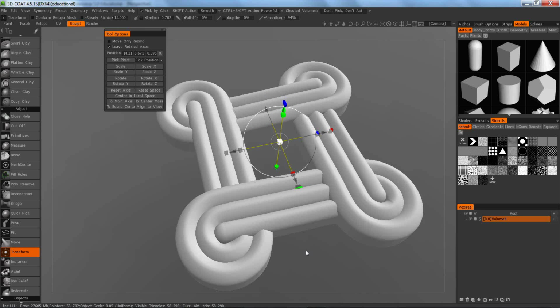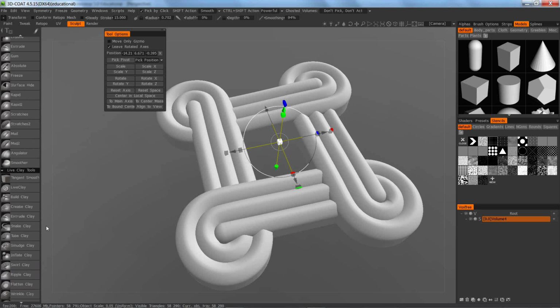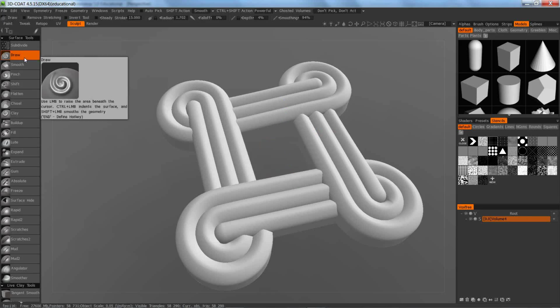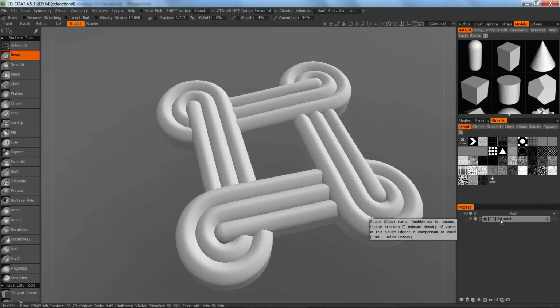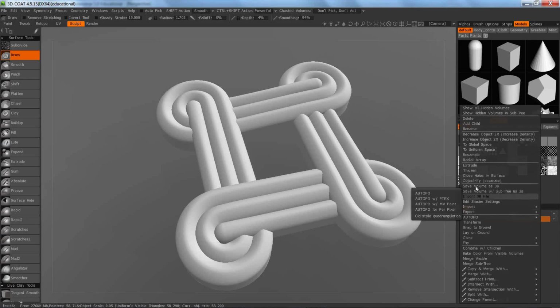The next thing I'm going to do with this is go back and put it back onto a regular drawing brush. I'm going to change the resolution of it. It looks fine right now, but it's not. Once again, this software, 3dcoat, was actually engineered as a painting program. It's to paint clothing and whatnot onto models. So it's estimating Rhino's mesh beautifully right now to show you what we have. But it's not really what 3dcoat sees. To get a really good mesh to work with, we have to make it much denser. So I'm going to right click on this and hit resample.